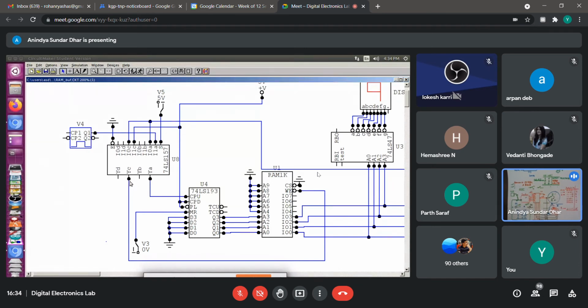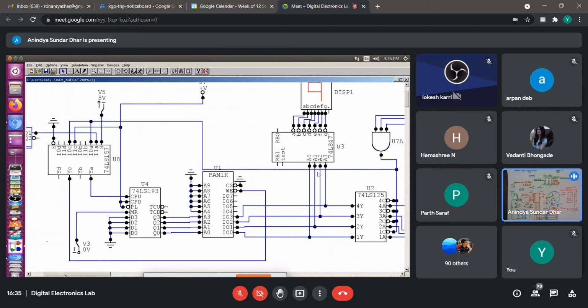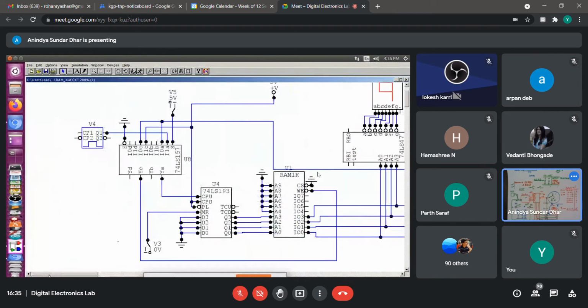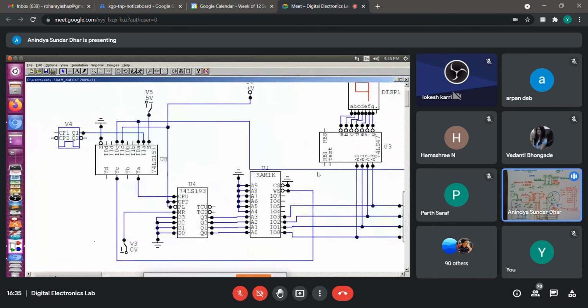Whether I will make write enable high or low, that is coming through two lines. So you see how I am selecting. Select switch I have controlled manually here right now. So this clock can take two different sources. If I make this one high, it will take from this pulsar. Otherwise, if this is low, it is coming from this AND gate, I believe. Okay, so just look at that. Yes, it is coming from the stretched pulse. Okay, so these are the two probable clock sources.